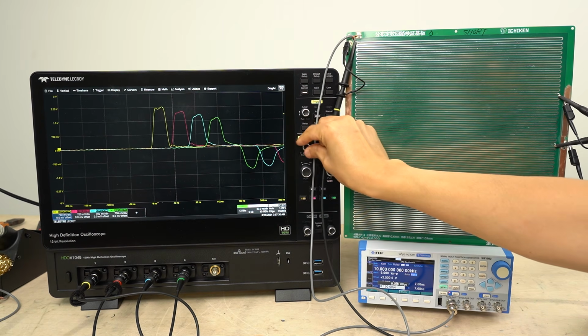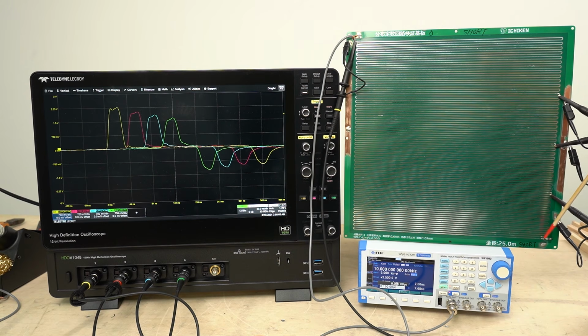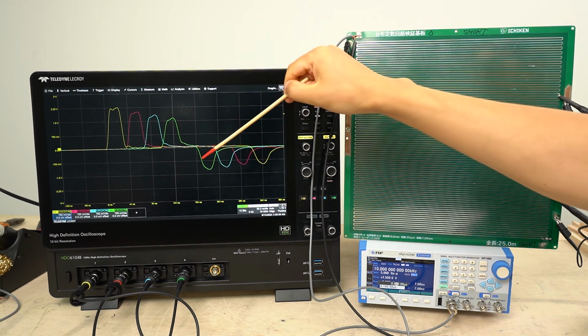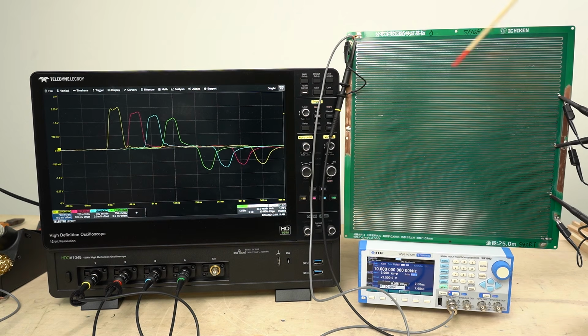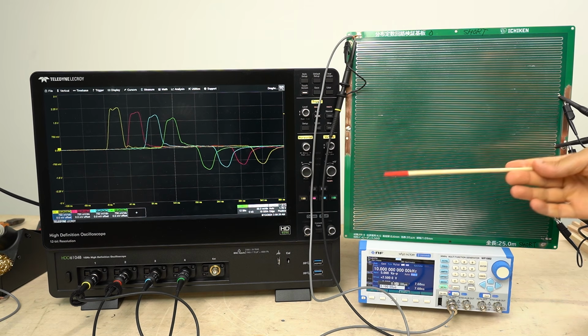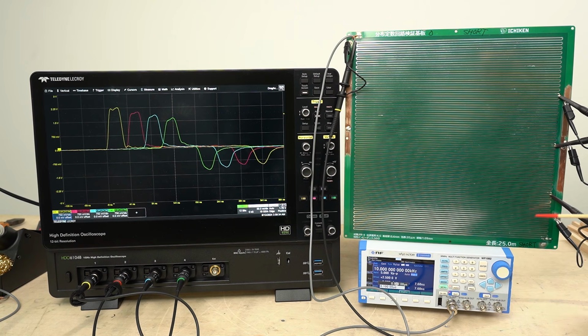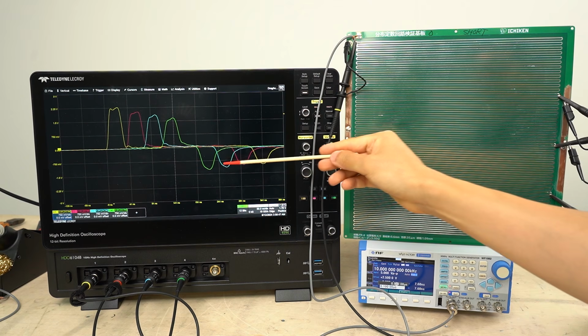Let's move the time base a little. The incident wave comes in and is reflected at this point. The reflected wave is inverted, and then it continues traveling back along the line toward the source. So the pulse travels down the line, reaches the end, and then reflects back as a negative voltage. That reflected wave then heads back the way it came, and at the 75% point, the waveform is effectively inverted there. Further along, at the 50% point, this is what it looks like.